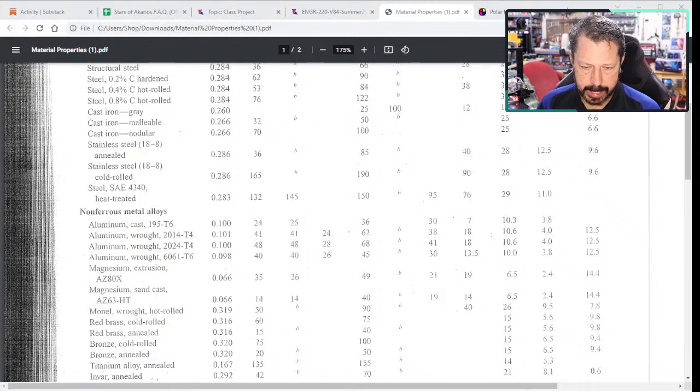So this is section AB. The torsional shear stress in section AB equals the torque in section AB times the outer radius of section AB over the polar moment of inertia of section AB. The internal torque we just found was 20 foot-pounds.